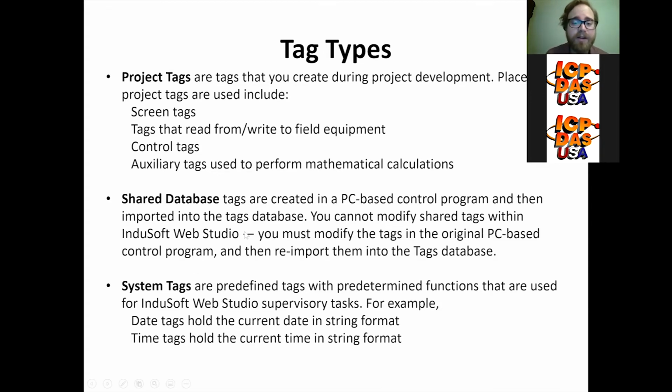Finally, system tags are predefined tags with predetermined functions that are used for supervisory tasks. So date tags hold the current date in a string format. Time tags hold the current time in a string format, and those are usually read-only tags like that. So hopefully that gives you not only an idea of what tags are in terms of Indusoft, but also a little bit of what Indusoft can do based on the kinds of tags.